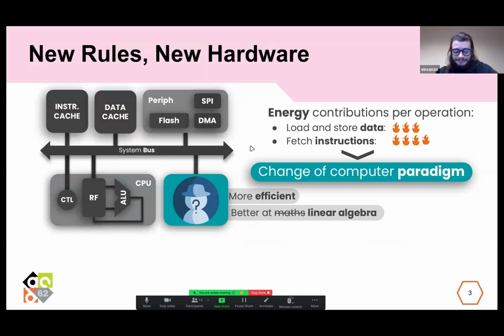And if you're here in this webinar, you know where I'm going with my discussion. We don't want ASICs, we don't want small GPUs or vector machines, because they are fixed. Although they are efficient, they are fixed. And what we know from the ML world is that hardware suffers from very quick obsolescence of IPs, because ML workloads change day by day, year after year, but the hardware designers cannot cope with this rapid change in the software stack. So we need some way that is more configurable.